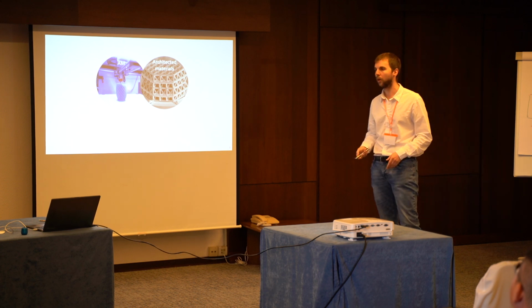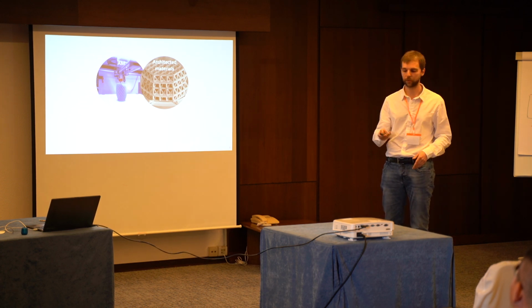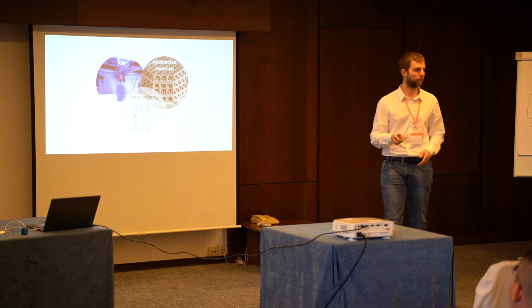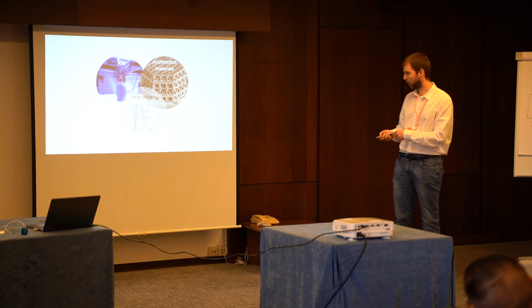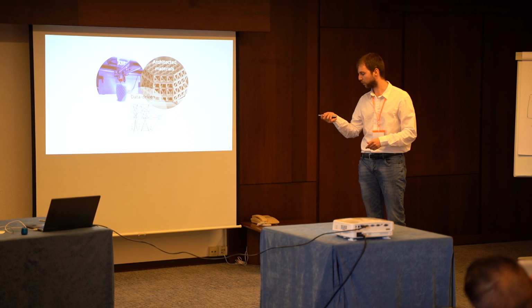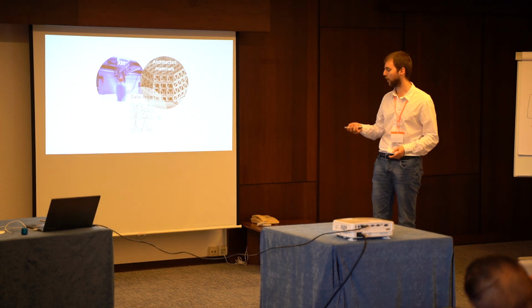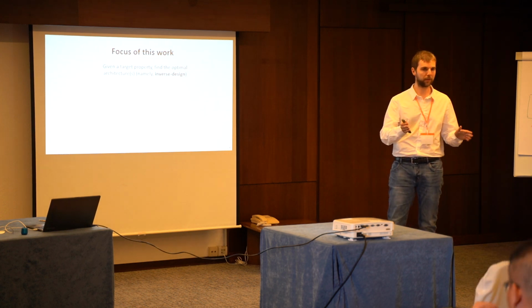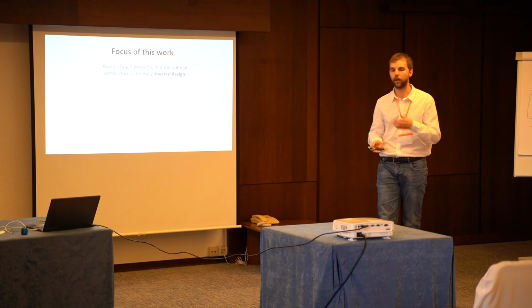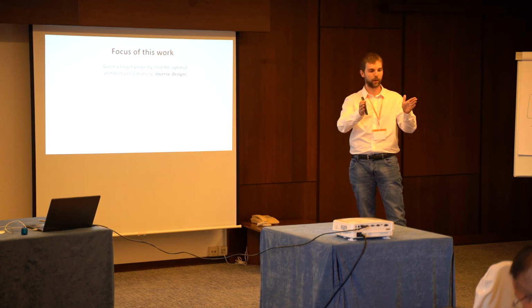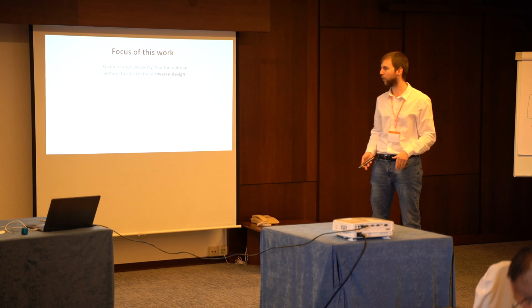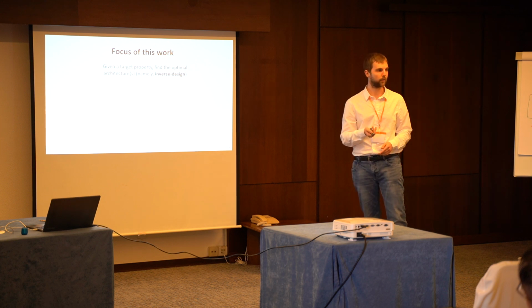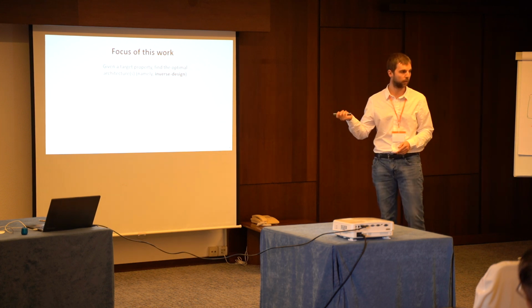So if we want to find optimal architectures for our materials, we can exploit the large amount of data that we can create, and we can gain knowledge from data-driven approaches. In this case, I've used deep learning. So the focus of this work is the following. Given a target property, for example, you want a structure which is compliant along one direction and different on the other, or you want to maximize the fracture toughness, you want to find the optimal architectures which satisfy this requirement, and this is called inverse design.